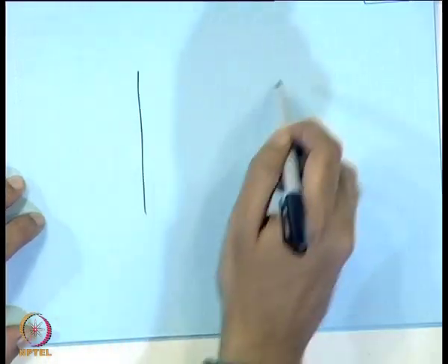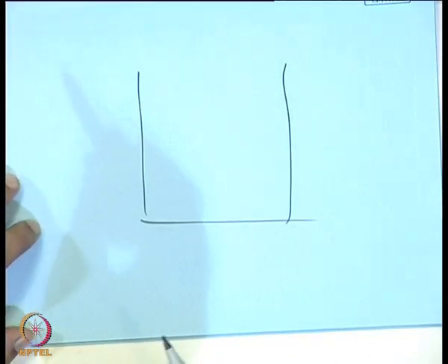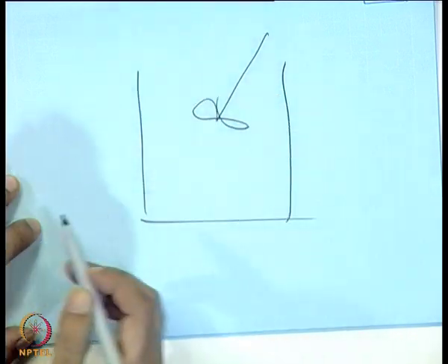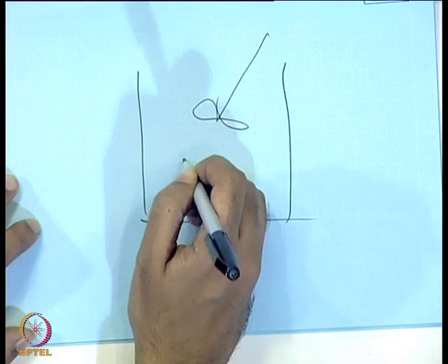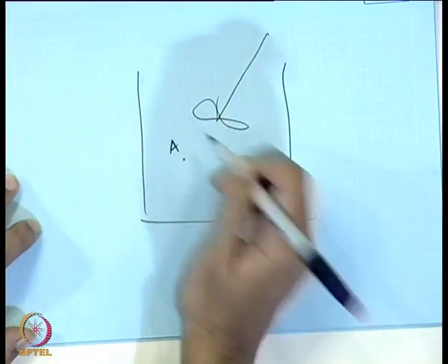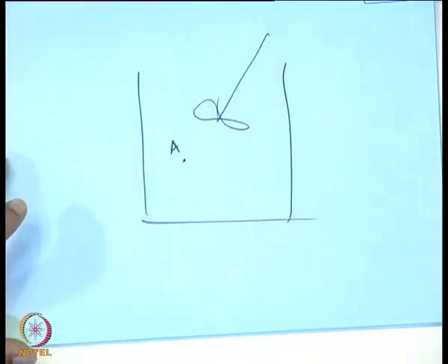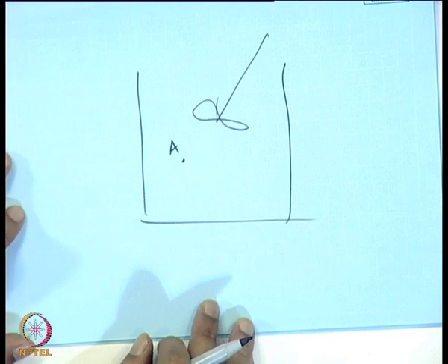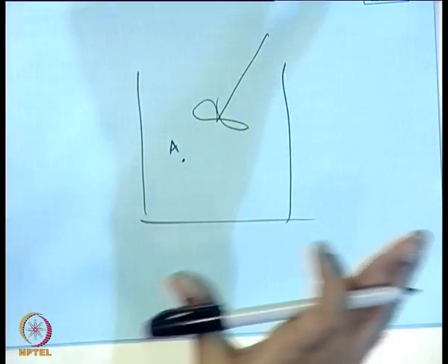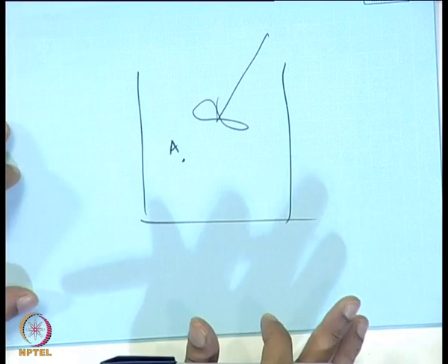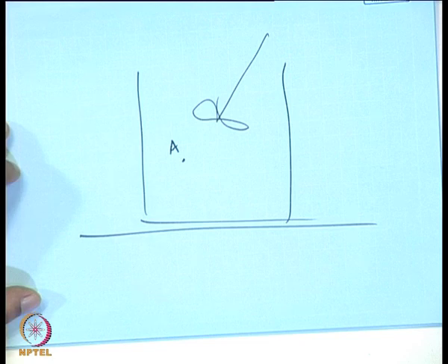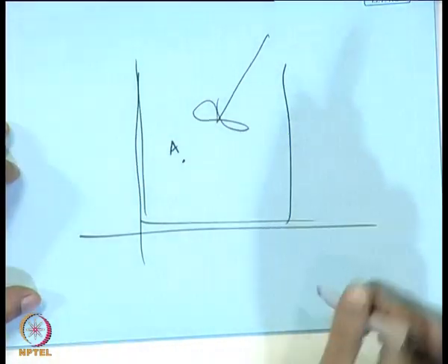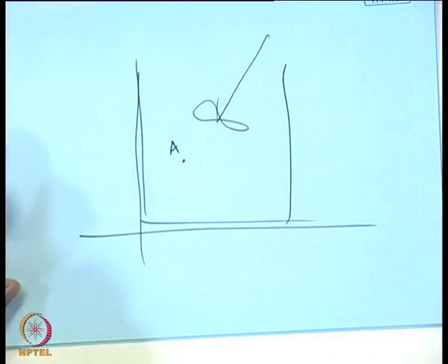Reactor runaway is essentially this: if you have a reactor like this, and these are large reactors, and you are mixing them at several points, and here is your reaction happening, A, everywhere. Now, these are real reactors, and there are different kinds of perturbations and disturbances. There could be disturbances on the floor, in the jacket, on the side, different disturbances in different places.